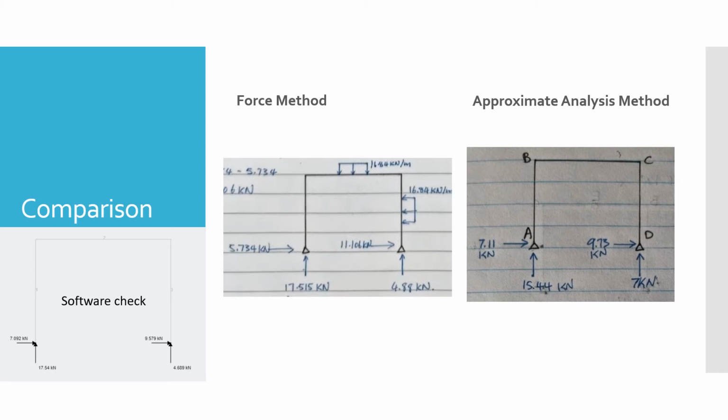And next I constructed my moment equations for the primary structure using the load conditions I got from my student number, as well as the moment equations for the redundant structure using the virtual load of 1 kilonewton. After obtaining all of the moment equations, I applied them to the compatibility equation in order to solve for the horizontal displacement at point A, as well as the linear flexibility coefficient, after which the real horizontal reaction force at A was gained.